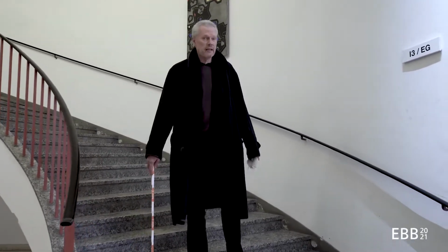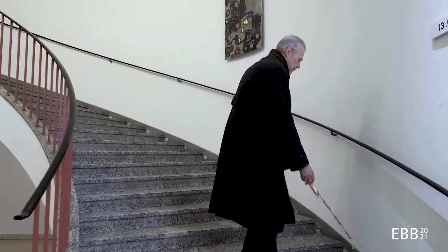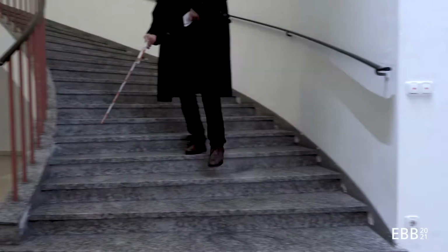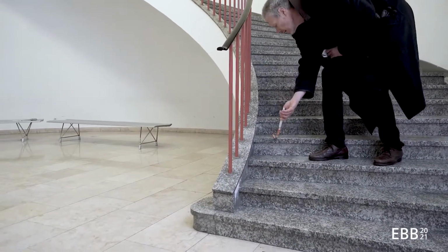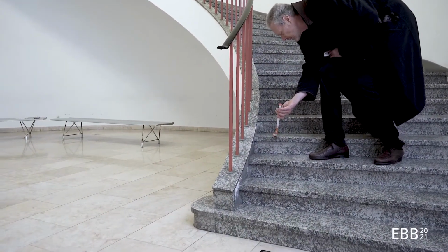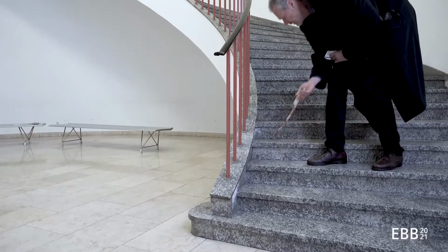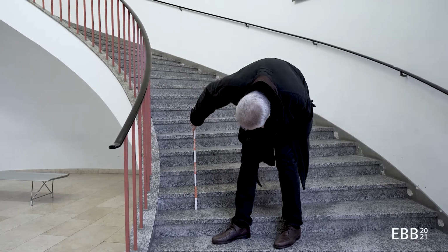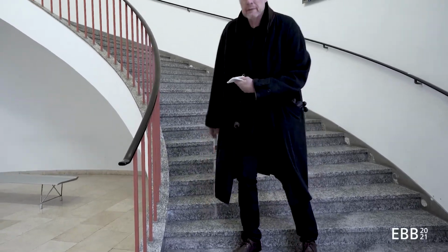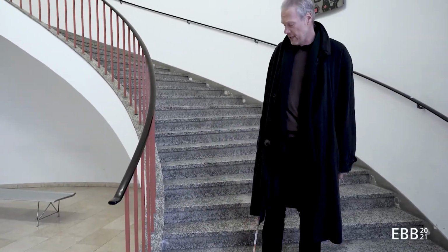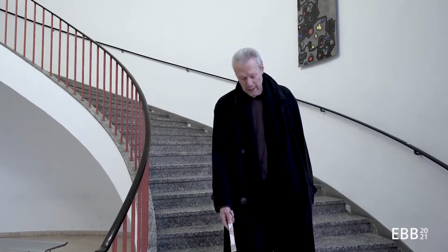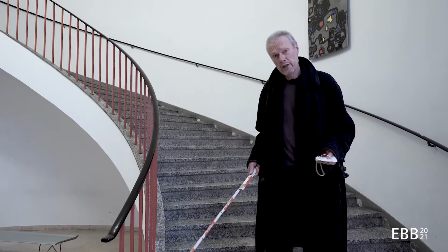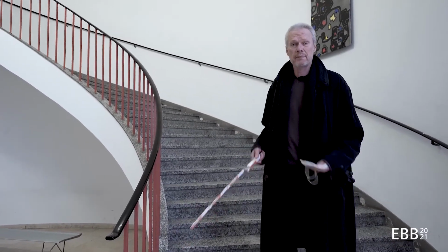width of the stair is changing. It's wider here, about 42, and on the other side it's 27, and all of this for about 14.5 as the height of the stair. So there's a walking line here, and on the walking line the relationship between rise and step is ideal.